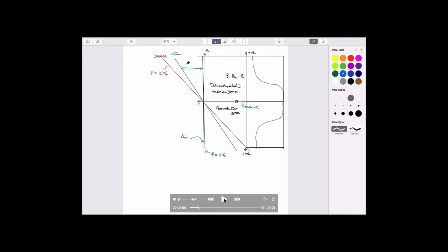And according to those pressures, the differences between water pressure and air pressure above the water table and water pressure and DNAPL pressure below the water table, we can define those capillary pressures changing with depth, and you've done an assignment to deal with that, and draw the capillary pressure versus saturation curves, which are shown on the right-hand side.